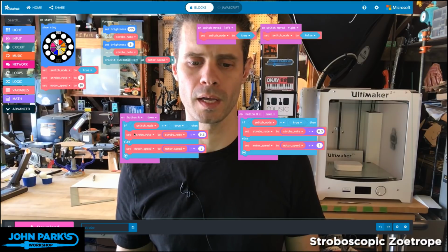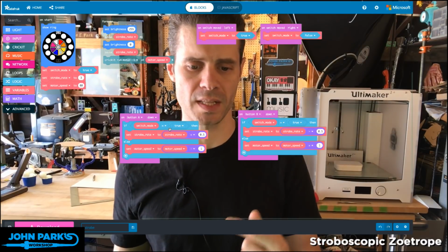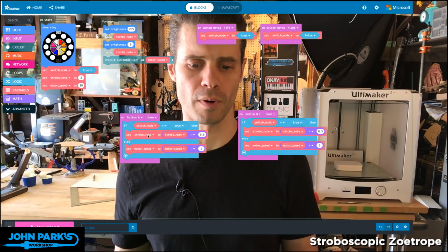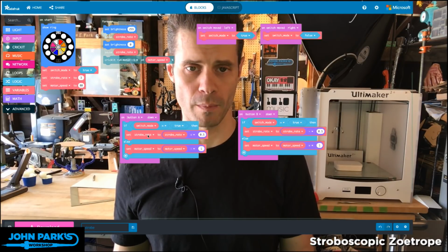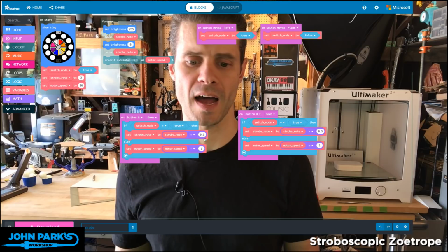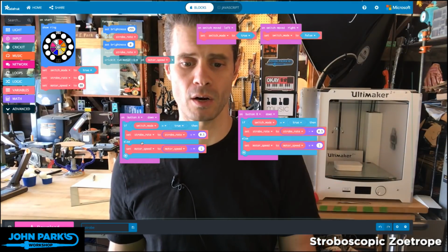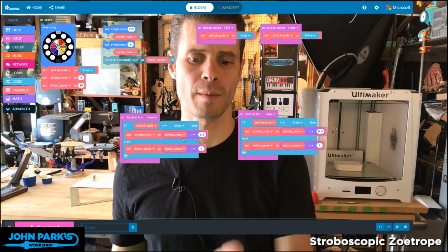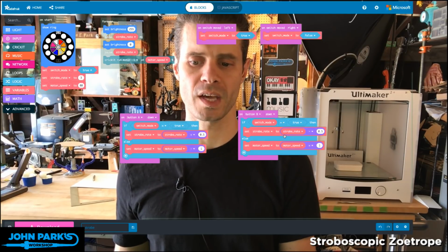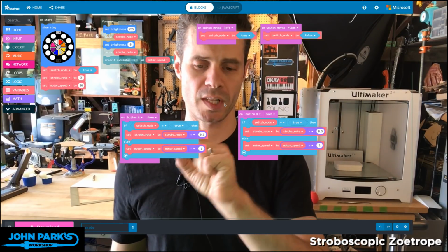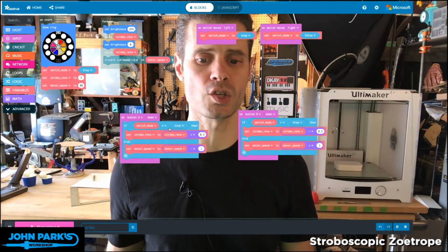And so in the case of the switch being set to the left, what the button press does is it changes the strobe rate to increment by 0.5. So the same thing we just showed a second ago with that myFoo variable, except here I'm taking the strobe rate to strobe rate plus 0.5, or if I hit the other button, it goes strobe rate minus 0.5. That's when the switch is to the left. When the switch is to the right, then this condition is no longer true.